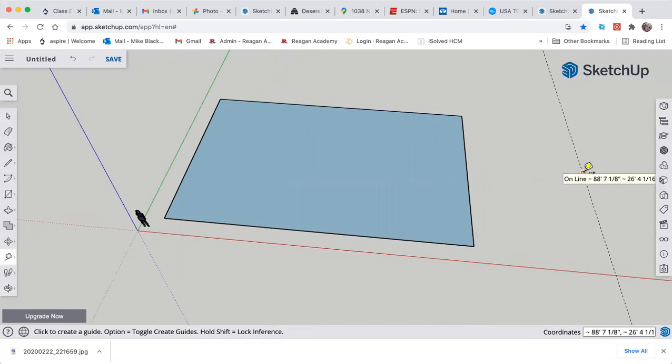If I want to make a garage, your typical or standard size is for every car you do 10 feet. So if I want a 2-car garage, I would do at least 20 feet. If I want a 3-car garage, 30 feet. And I can go bigger than that. Most garages are a little more than 20 feet wide if it's a 2-car garage. And then the depth of a garage is always going to be 20 feet or more. That is code or standard that you have to follow.